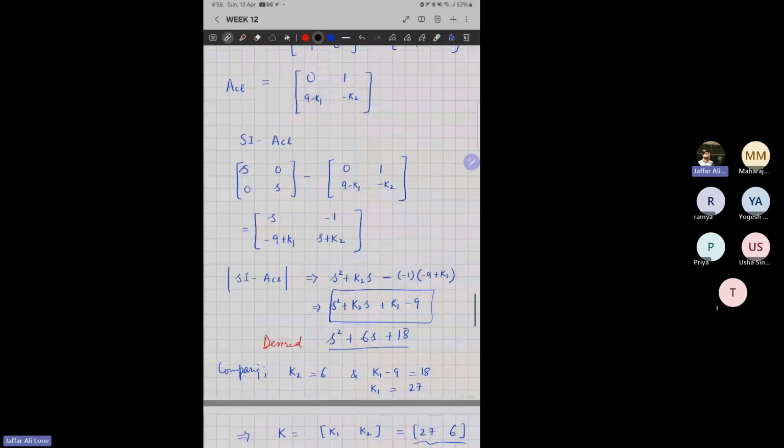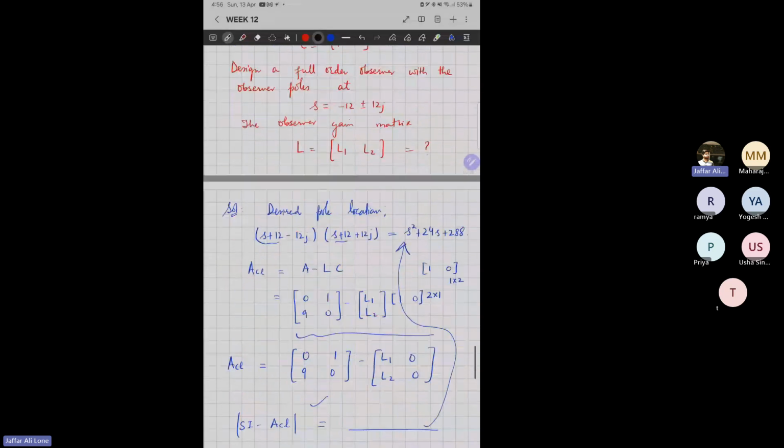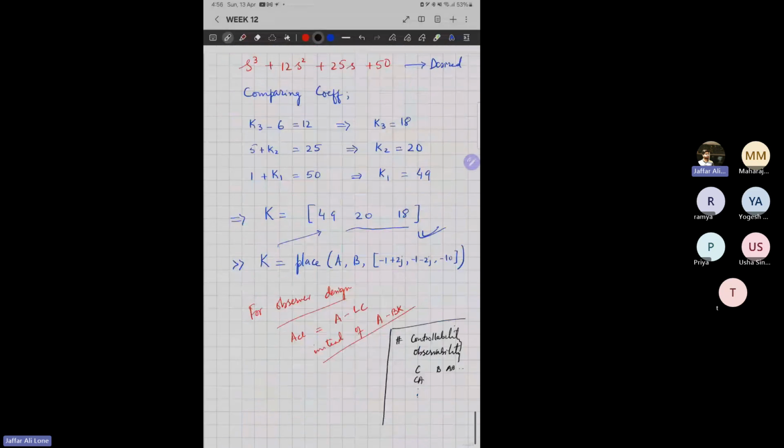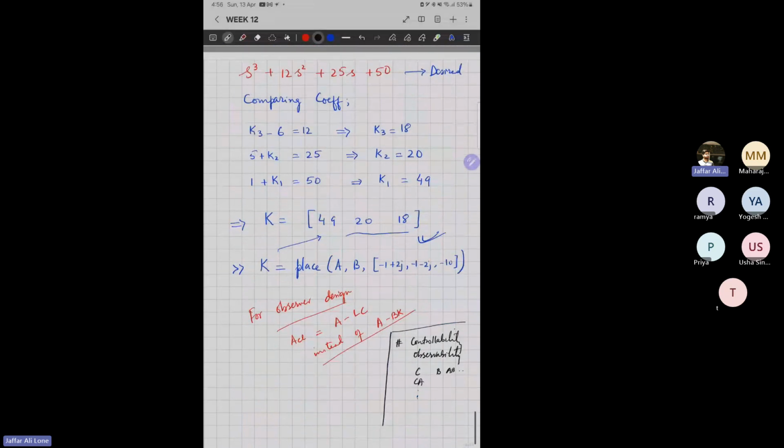The third question is you have to find the controllable or uncontrollable eigenvalue. Again, as I told you, you can use the PBH test, which is [lambda I minus A, B]. You just have to calculate the eigenvalues, put the eigenvalue here, and find the rank. Either you can use that, or you can find the transfer function, or you can use the controllability decomposition similarity transformation.